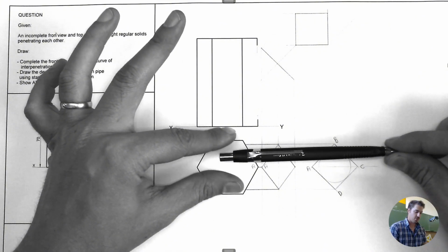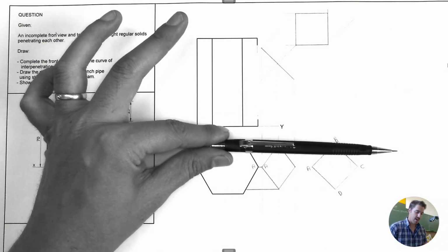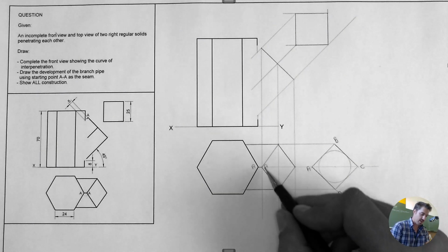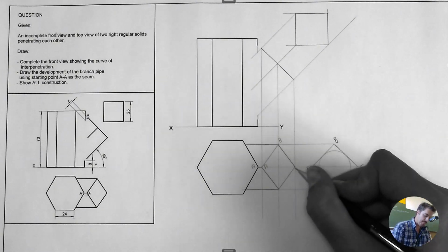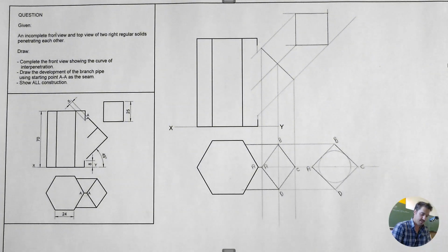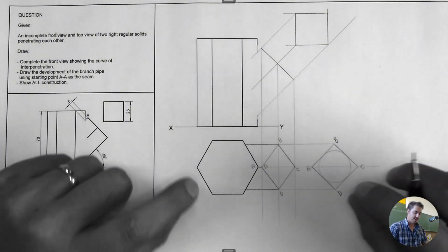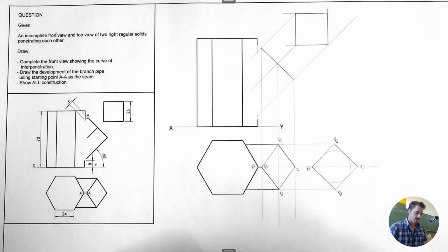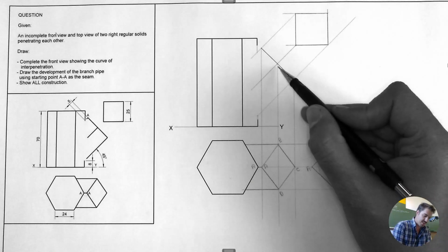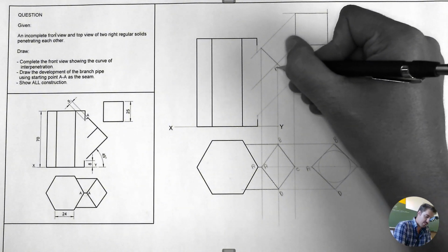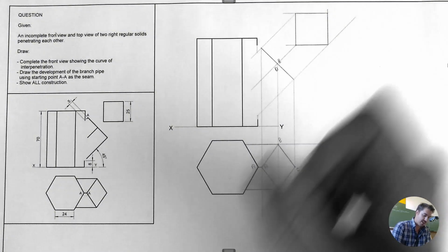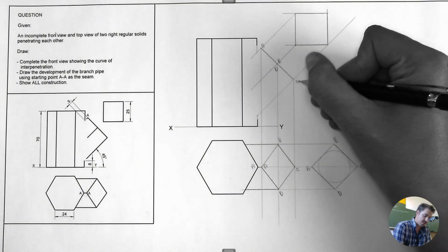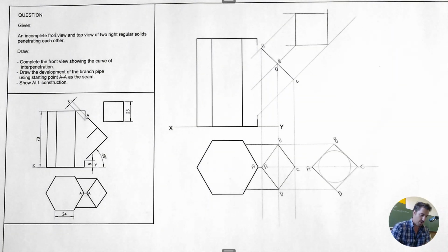I'm taking it onto point A, and I'm lifting it up. So point A is closest to me. So that's A, B, C, and D. Now this entire top view is now falling over the XY, so it's then the front view, which means this line that comes down here is going to be point D. At the back of that you'll have B, A is going to be at the top there, and C is going to be down here, like we've already established.